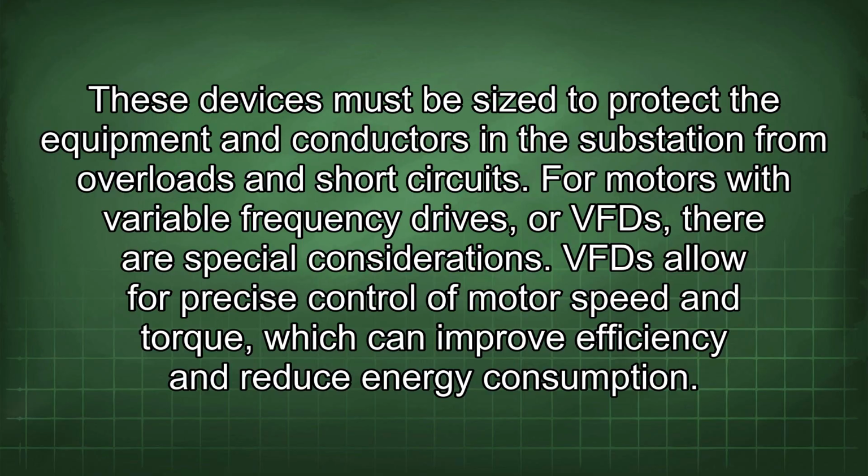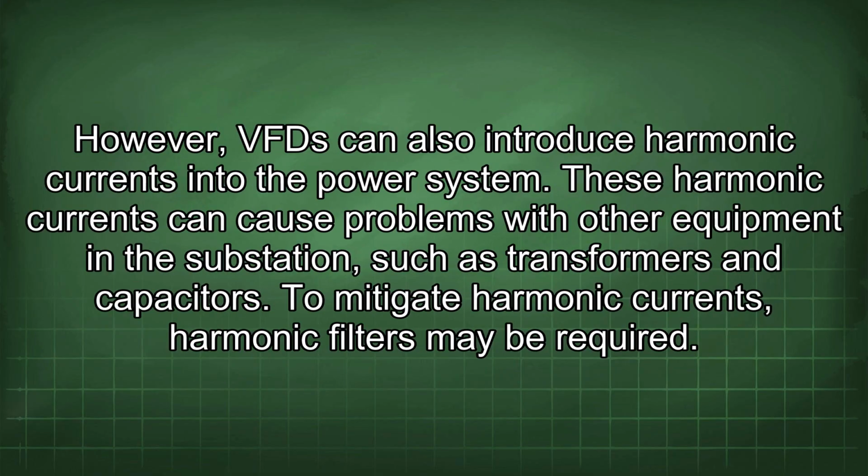For motors with variable frequency drives, or VFDs, there are special considerations. VFDs allow for precise control of motor speed and torque, which can improve efficiency and reduce energy consumption. However, VFDs can also introduce harmonic currents into the power system. These harmonic currents can cause problems with other equipment in the substation, such as transformers and capacitors. To mitigate harmonic currents, harmonic filters may be required.